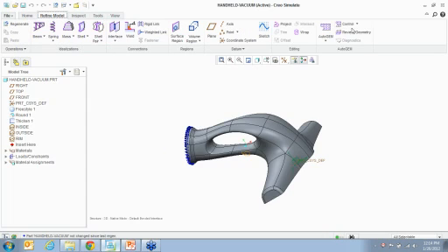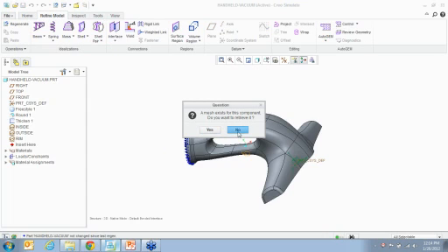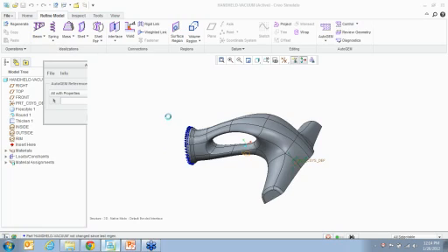So right now I'm going to try and create a mesh in here. Let's go to AutoGEM and create a mesh. It's going to be a little while before it creates the mesh, because the part is extremely thin and we're trying to create solid elements. I ran this before, and it created about 10,000 elements for me. It's just going to be a couple of seconds.